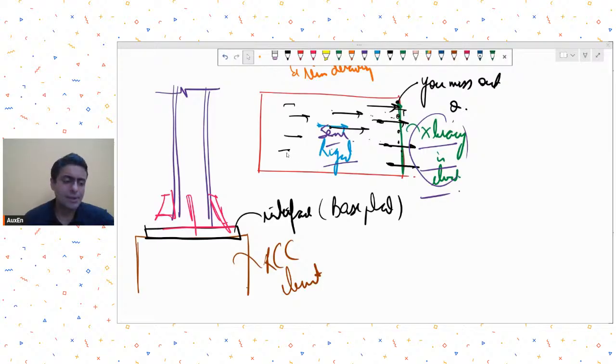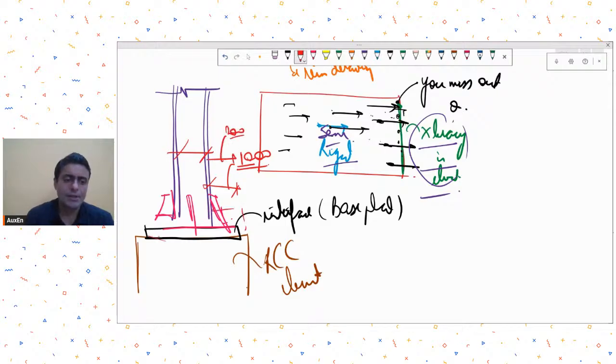So you will see that the base plate, which is usually governed by bearing, will not have a very large offset beyond the steel column face. What I mean to say is it will not happen that you need a 1000 offset for this base plate. Why? Because even though the column size is quite large, maybe a 200, 300 offset, and you are able to satisfy bearing.